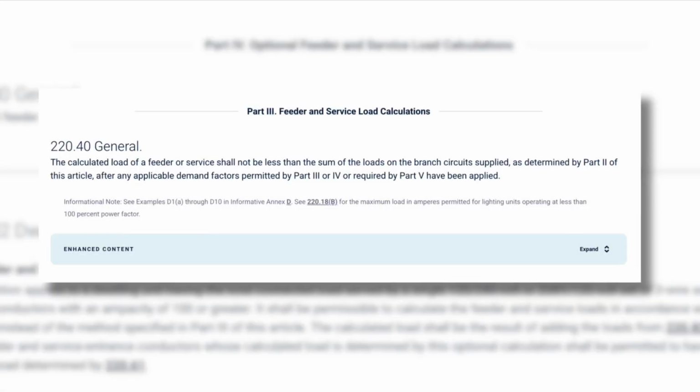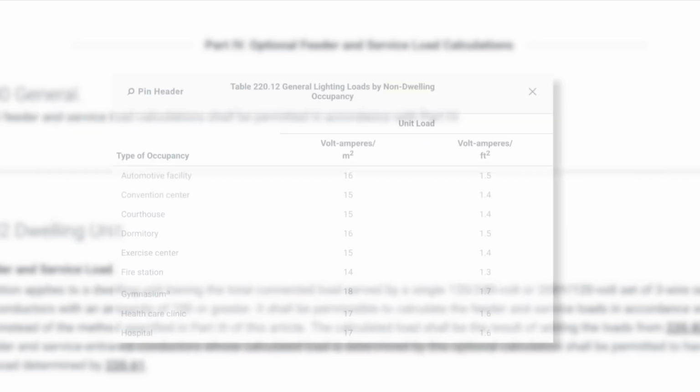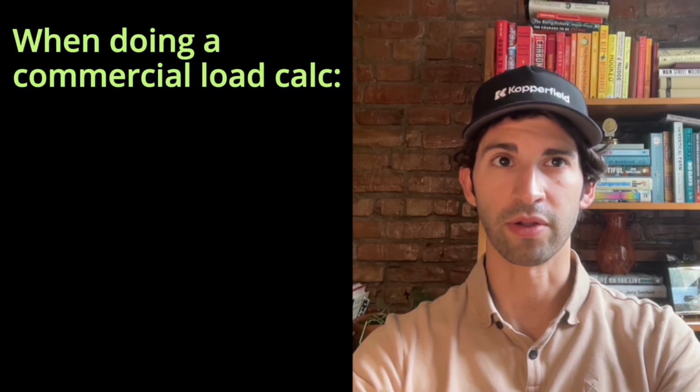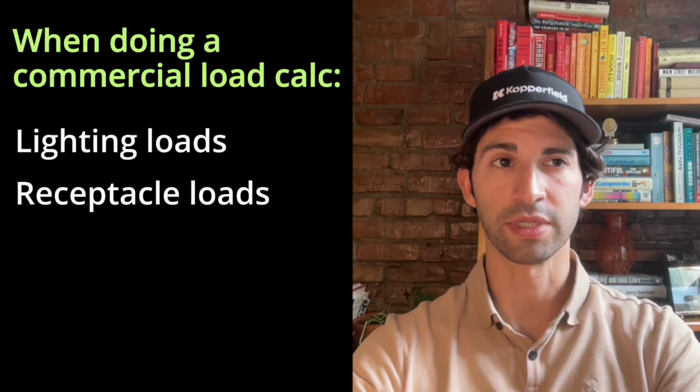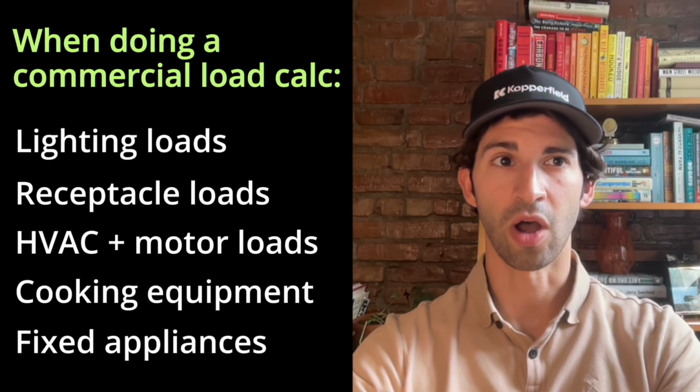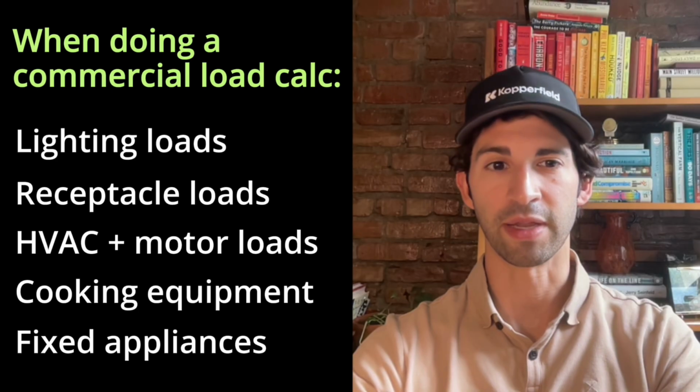The NEC outlines the standard method for commercial load calcs in Article 220. For example, in NEC 2020, occupancy types are described in Table 220.12. This is different from the residential calculation that often uses the simpler optional method. When doing a commercial calc, you'll want to make sure you specifically cover lighting loads, receptacle loads, HVAC and motor loads, cooking equipment, and fixed appliances, all with the appropriate NEC specified minimums.